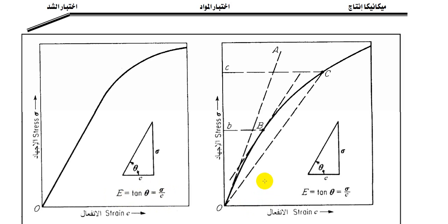In this curved line, as you can see right in front of you, the curvature will occur in this shape, or scheme, or diagram, expressing the point of elasticity as well as the point of ultimate tensile stress, denoted by the UTS abbreviation. So the tangent line here is the proof stress line, intersecting with the point C to express the proof stress, at which the material is guaranteed not to fail at certain limits. In this point, the material will not fail at this limit.